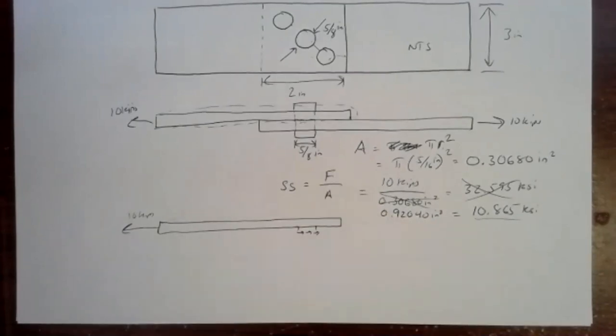Go ahead. That being said, we're not going to have to worry about rivet spacing or transverse pitch, none of that. No, we're not going to have to worry about strict layouts or anything like that. That's more of an efficiency issue as far as keeping the repair small. In principle, if you had infinite space to work in, it wouldn't matter what you did as long as you didn't get close to those limits. So you want to put an inch between each rivet? Sure, go for it. Have a 10-inch edge distance. It's fine. It wastes a lot of material, but it's never going to be a problem from a stress point of view.